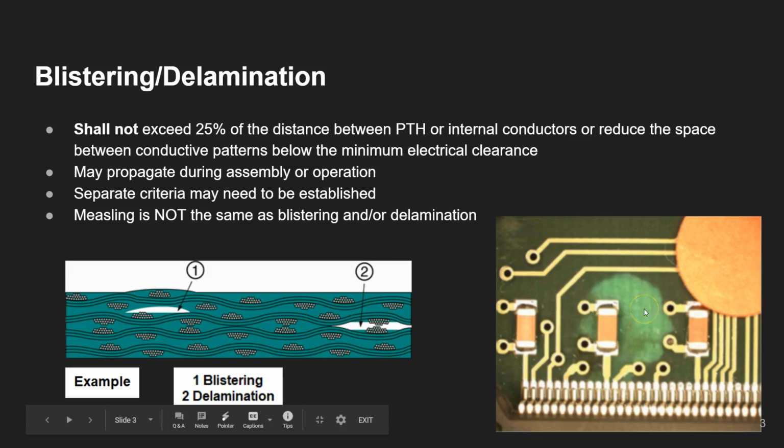So the cause of delamination or blisters are due to thermal shock or excessive thermal stress during soldering, or due to manual soldering, rework and repair process, moisture in the board, poor lamination process, etc. Now, the question is, how can we prevent delamination and blistering? So the prevention can be done by baking of board prior to thermal processing, or by keeping the PCB dry in storage area.